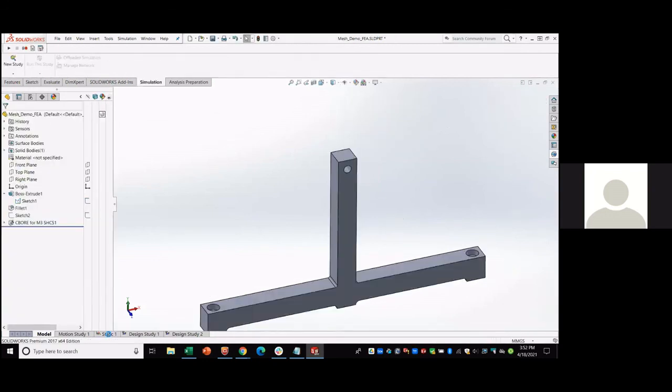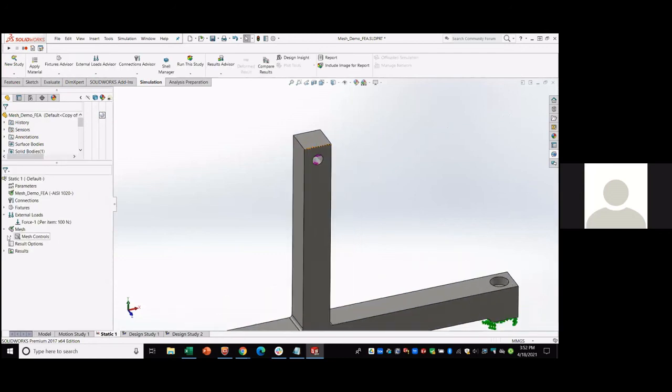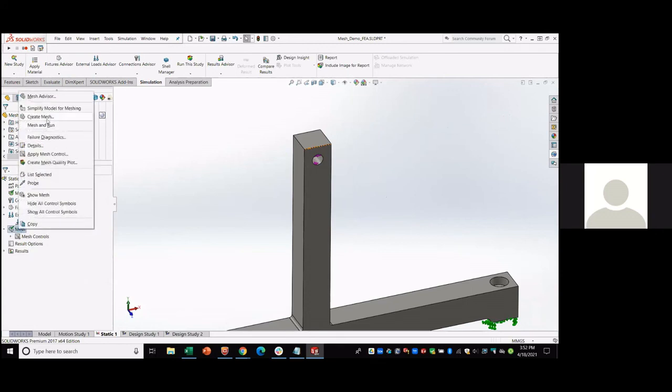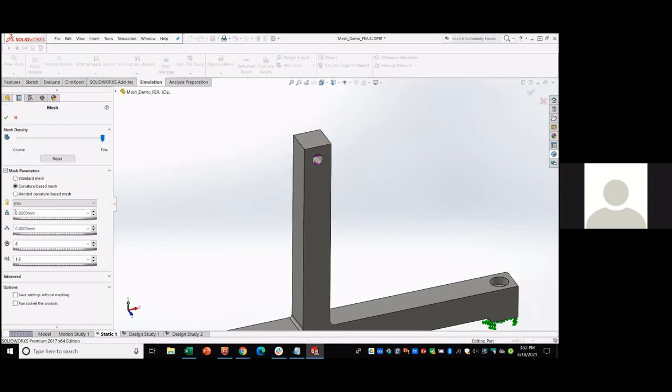But for stuff like, if I go to my static model where my mesh size is controlled by a parameter. So you go to create mesh. The mesh size is highlighted. Let's see, if I go to standard mesh. Okay. So notice how under the standard mesh option, the global element size is grayed out. I can't change it because that's part of the design study.